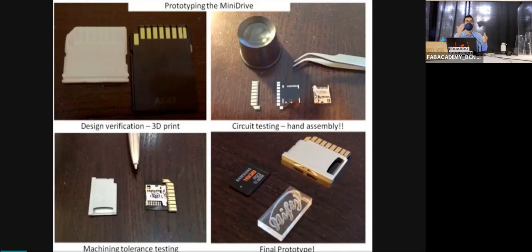Everything in the computer, you can easily assemble. Objects can go through each other in the computer. In real life, no. Also, we have tolerances. For example, we have seen a lot of chairs that look really cool in the computer, and when you want to sit, the chair just bends on the back because it's not stable. The only easy way to test a small model of a chair is a really silly thing: make the laser cut chair small and put your phone on it. More or less it's the same scale and weight of a human on a normal chair.